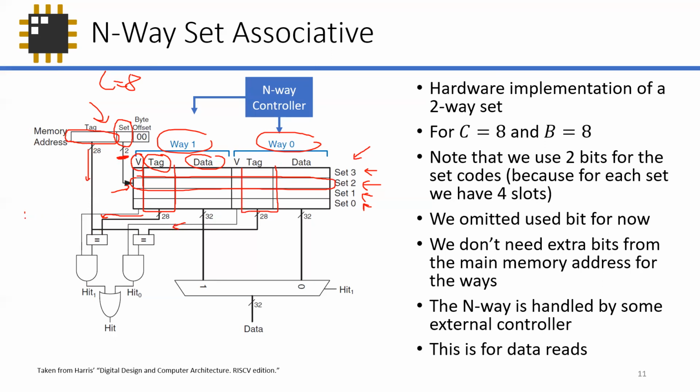In Verilog, it's just: tag of memory is equal to tag of the cache, tag underscore C, something like that. If they are the same, then you'll generate a hit. And of course, you have to plug in the valid bit as well, to indicate whether this was the data during startup or not. And if any of those match, then you have a hit.